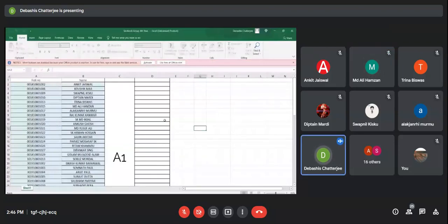So then your group will be a machine which is 3-phase, 230 volt line to line. All are line to line voltages. 50 hertz, 500 watt, same 736 RPM, 0.8 power factor, and temperature rise 45 degree.